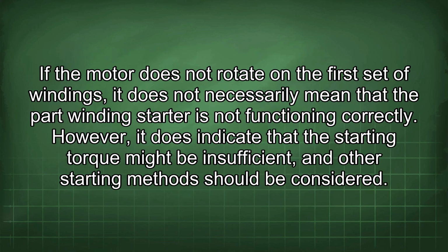If the motor does not rotate in the first set of windings, it does not necessarily mean that the part winding starter is not functioning correctly. However, it does indicate that the starting torque might be insufficient and other starting methods should be considered.